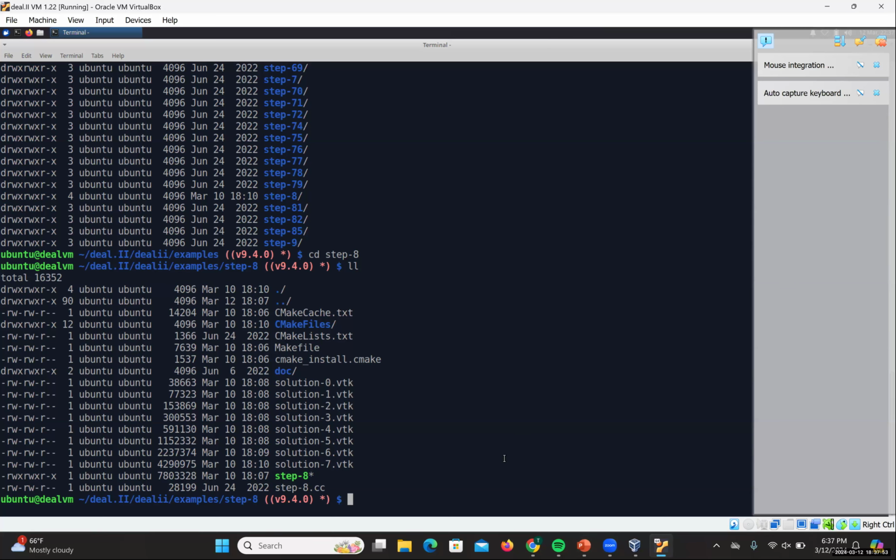Okay, so if we look at the main program in this C++ code, I'll just bring it up. Ignore this part for now, but basically what are the steps in a linear finite element problem? We're going to assemble our system, which is calculating that big matrix K that I talked about. We'll solve it, invert the matrix, and then output the results.